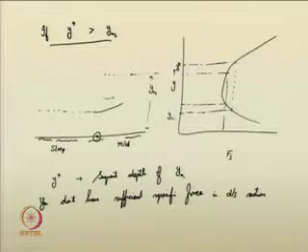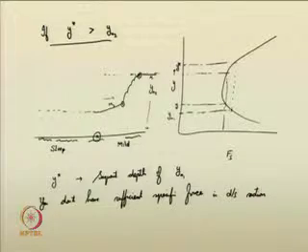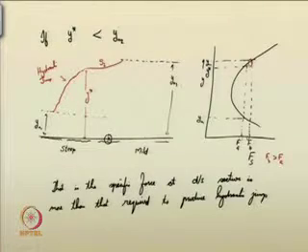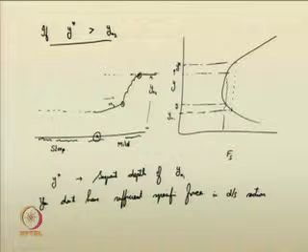Up to this depth the M3 profile will occur, here a jump occurs and it attains the specific force. So, now you can see that at both this location and at this location, they have the same specific force, that is the requirement for a hydraulic jump. So, this is how you identify the location of the hydraulic jump for a situation where the normal depths are not sequent depths. As we have seen in the previous case, the jump is pushed upstream, and in the subsequent case we have seen the jump is pushed downstream.